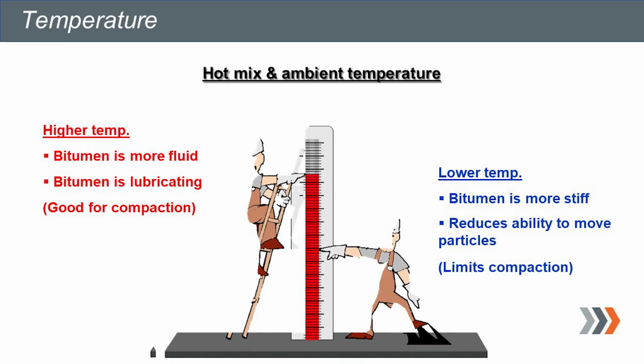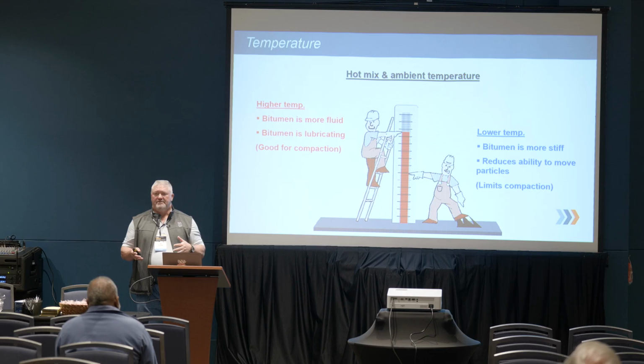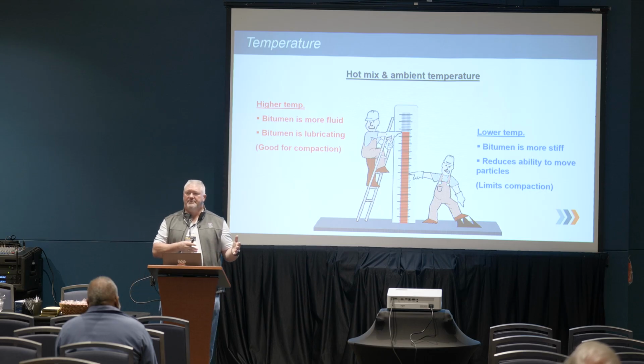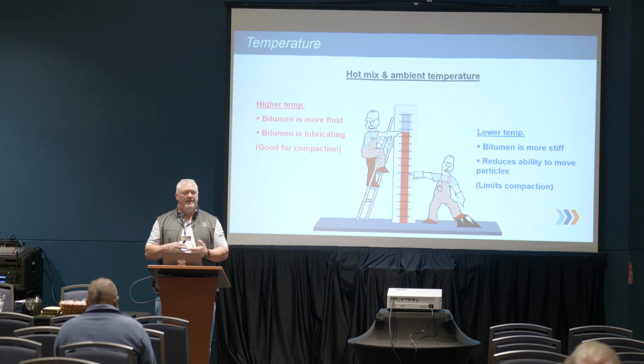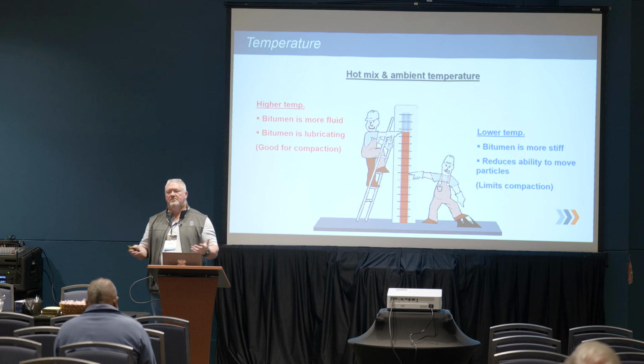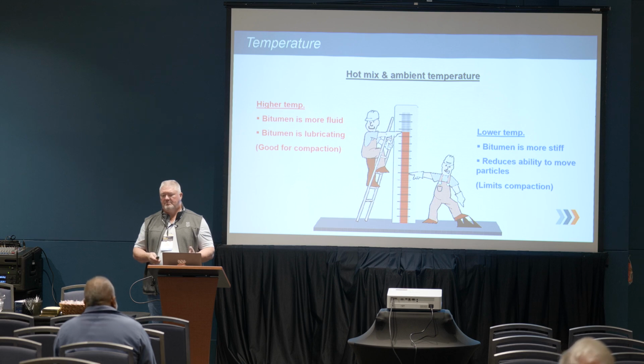Temperature is our friend when it comes to asphalt. When it's hot, it's easier to compact, easier to do handwork, less segregation. When things start cooling down, we have a harder chance of getting compaction. We do handwork, we start segregating the material, we get some surface segregation, and all those large stones are not going to compact, and we're going to start raveling things up.